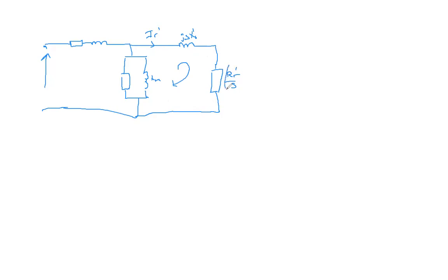We have this is our rotor equivalent effective resistance, and this is the rotor current. So the power supplied to the rotor is equal to IR squared times RR prime over S. Simple, right? But this is the power supplied to the rotor.